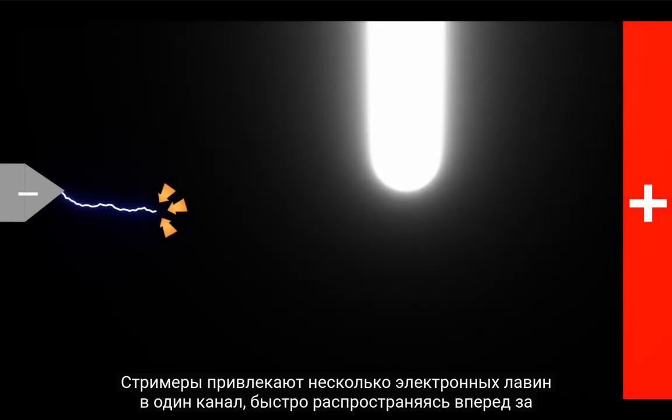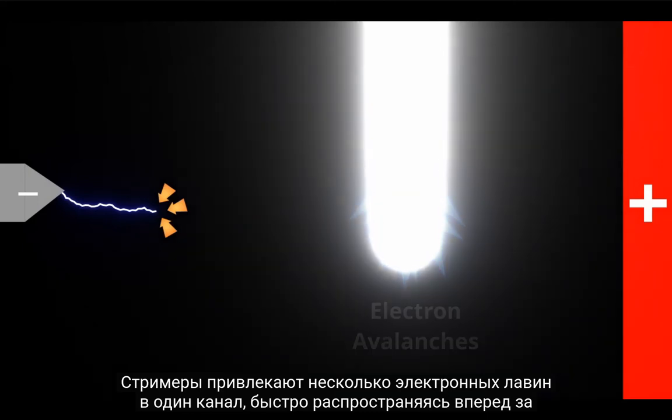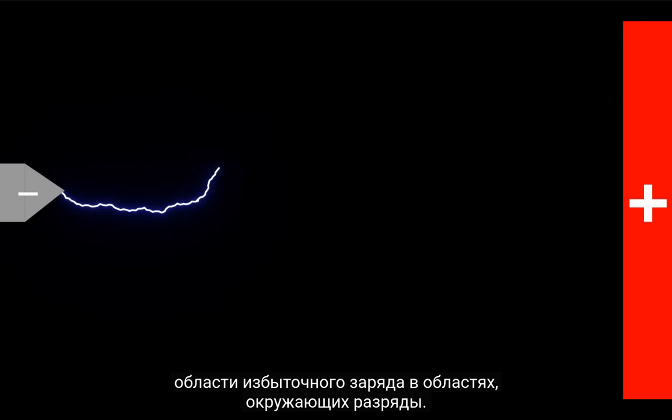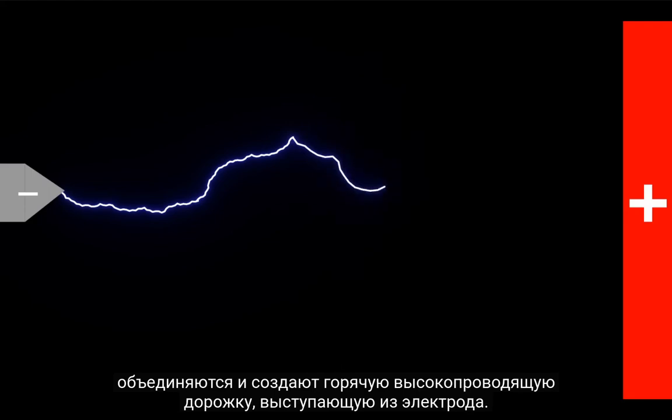The streamers attract multiple electron avalanches into single channels, propagating forward quickly via photon emissions, which lead to photoelectrons producing new avalanches. The streamers redistribute charge within the surrounding gas, temporarily forming regions of excess charge in the regions surrounding the discharges. If the electric field is strong enough, the individual currents from multitudes of streamers combine and create a hot, highly conductive path that projects from the electrodes.